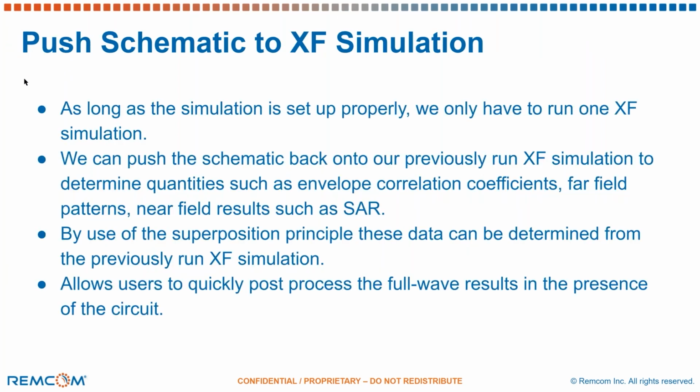Finally, as long as the simulation is set up properly, we only have to run one XF simulation. And then we can push back the schematic onto our previously run XF simulation to determine quantities such as envelope correlation coefficients, far field patterns, and near field results such as SAR. By use of the superposition principle, these data can be determined from the previously run XF simulation.